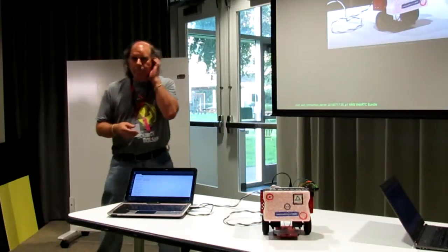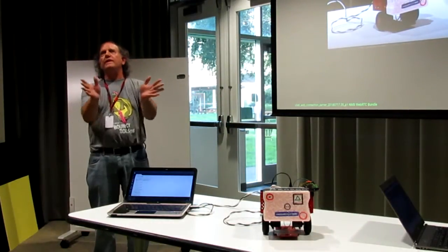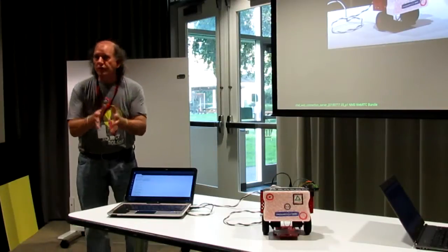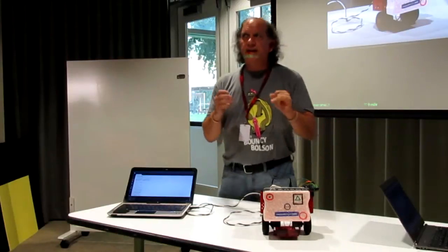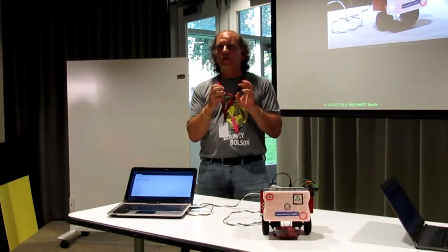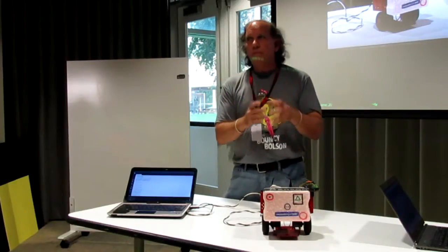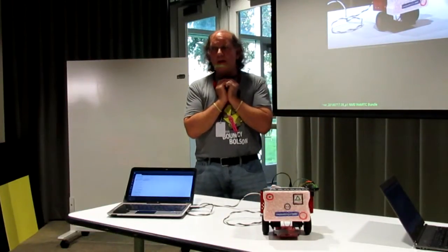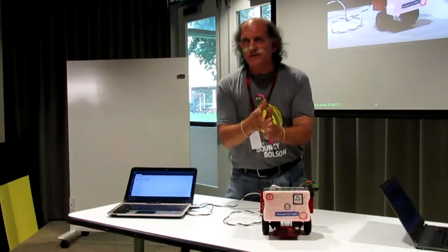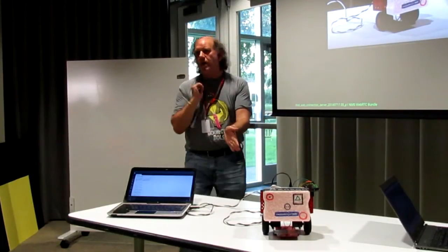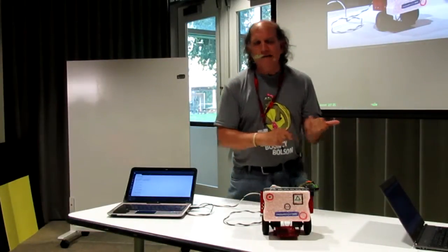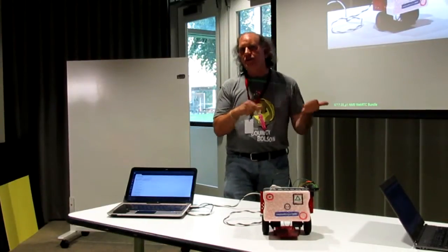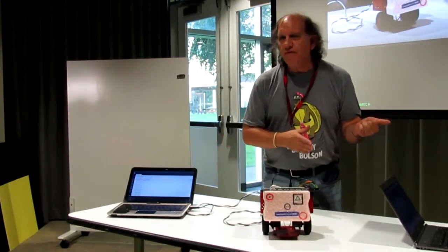And so I'm programming it to follow a 45-degree corridor towards the direction that it goes. In other words, this reads the GPS and subtracts the target latitudes and longitudes to determine what direction I need to go in. And so I go forward, and you get the bearing 0 through 360. 0's north, 180 south, 90's east, 270's west. And so if my target latitude is higher than my actual, and my target longitude is higher than my actual, I need to travel northwest.